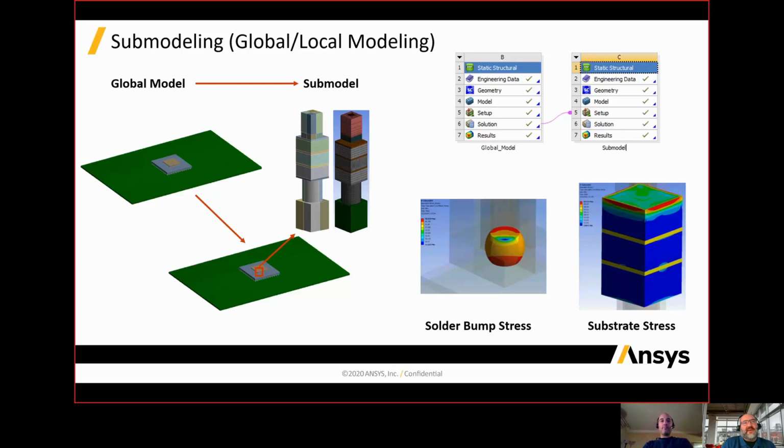So this is usually a one-way approach. We think of a global model informing what's going on in a local model. We're actually working on an approach in LS-DYNA that's a co-simulation, if you will. So imagine having a global model, maybe with a simpler representation like a beam, and then passing that to a local model, and then accounting for very fine level details, including things like fracture and other behaviors, and then passing that information back to the global model. So, we're definitely at the forefront of looking at new strategies and new approaches in this regime.